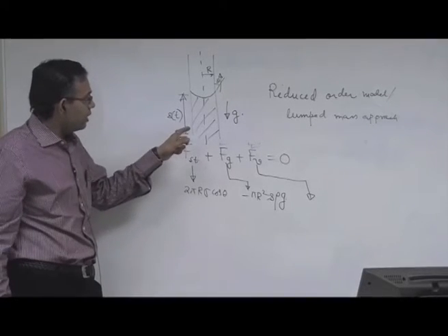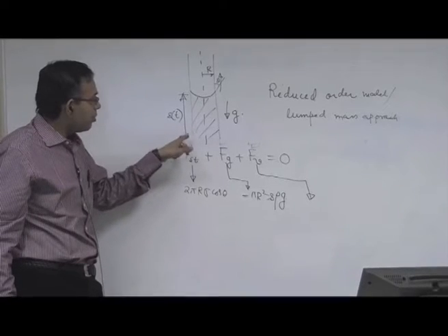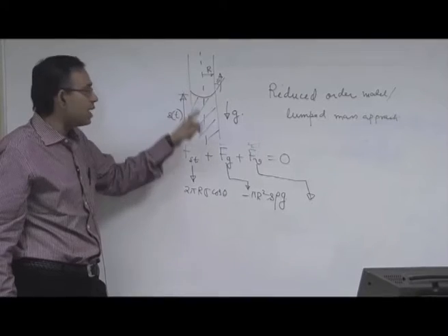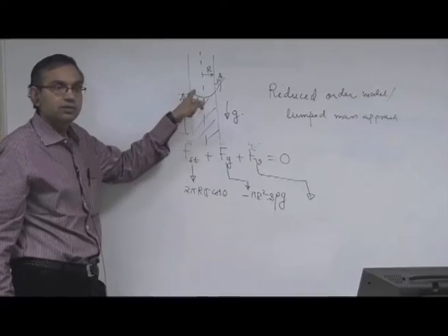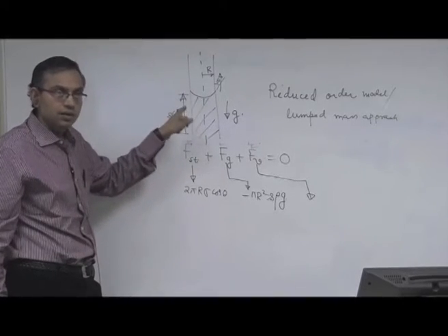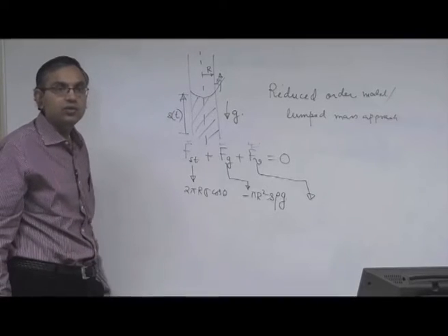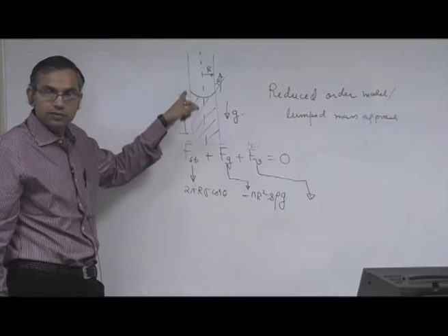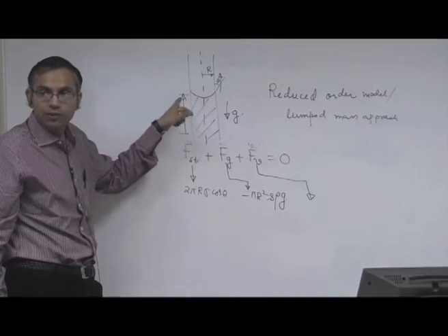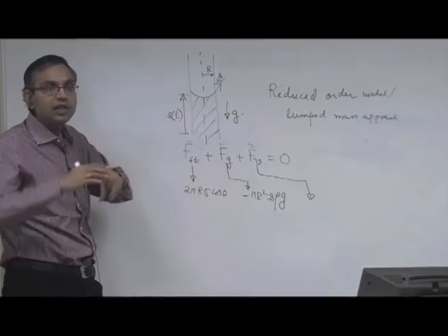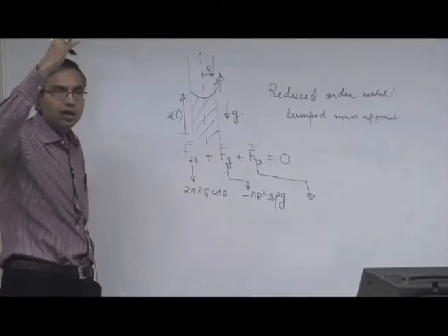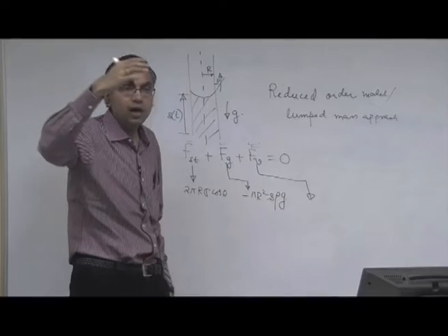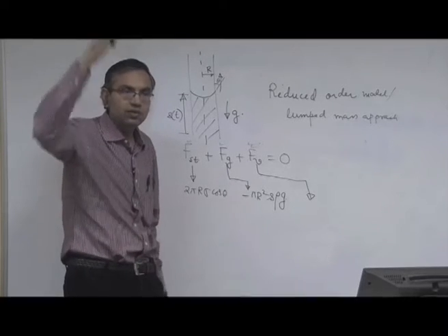So, first of all we can write it as tau wall into 2 pi r into S, provided tau wall is constant throughout, right. When is tau wall constant throughout? When the entire flow is fully developed, hydrodynamically fully developed. Then the velocity profile is constant throughout and tau wall is like the mu into velocity gradient at the wall. So, that is also constant throughout.